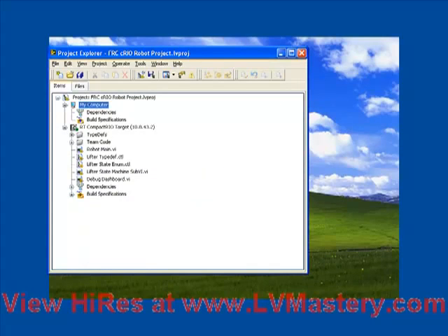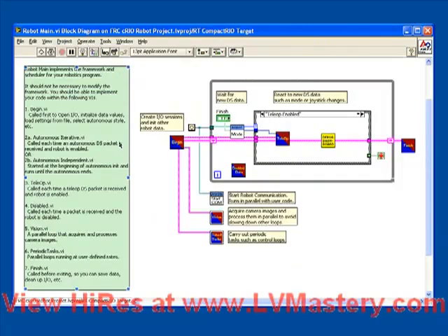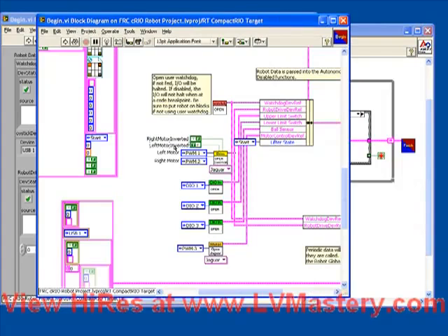So let's begin where we left off the previous installment, having just created a state machine code to drive a theoretical lifting mechanism. So if we open up our robot main, let's just review where we placed all that code. In the begin step, we opened up 3 digital inputs and a motor controller and wired all of them into a type def which we created specifically for our lifter.